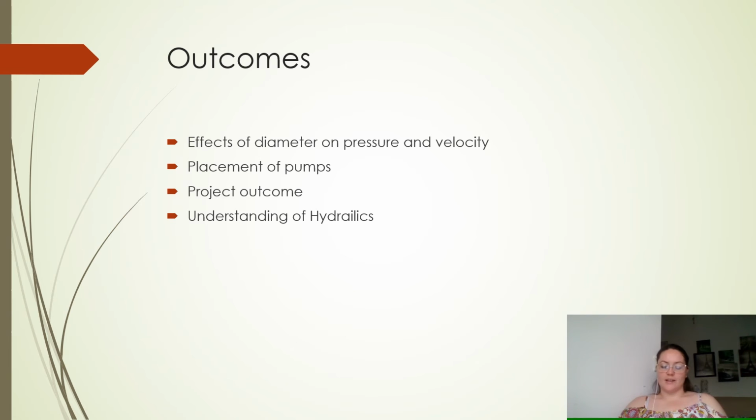Through the analysis I have learned that the diameter of the pipes affects the pressure and velocity. This also showed me how changing the diameter will allow the water being supplied to overcome resistance, such as at pipe 8, where I noticed that reservoir 7 is higher than the elevation of the junction that is supplying it. This needed a smaller diameter pipe so that it could overcome that to get the desired pressure and velocity. I also have to take into consideration the pumps.